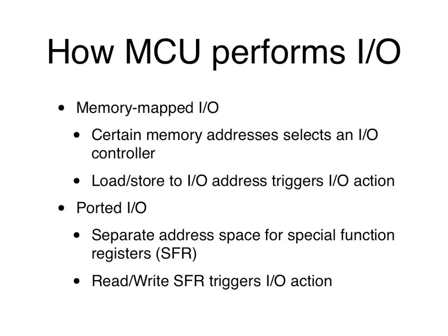So what memory mapped I/O does is say, well, these are empty locations anyway. Let us map those addresses to input and output devices. And that's how it can address those devices. It names those devices by mapping them to certain address ranges, and then each address may correspond to a different operation. So that's what memory mapped I/O does. You do reading and writing to those memory locations, and that triggers I/O to happen.